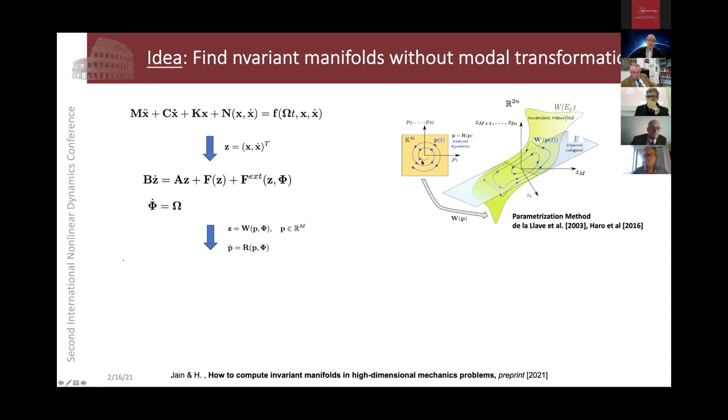And also we look to construct the dynamics in that parametrization space, and the right-hand side of the dynamics is unknown at this point, and we will try to pick it as simple as possible, basically a normal form approach. When you then take these two functional forms, first you need to know that the SSM exists, but we know under certain conditions, and you differentiate the first relationship in time, then you start getting a differential equation for these quantities. Then using the invariance of this manifold, as usual, this leads to a PDE, called the cohomological equation, which we want to solve.